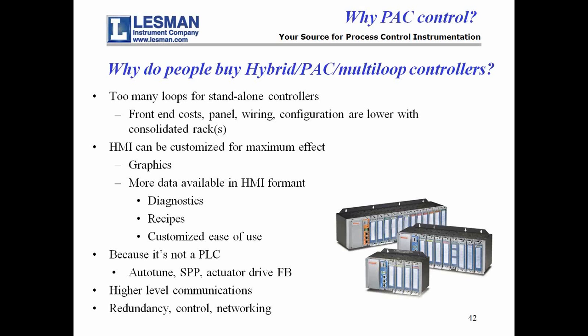And SCADA is really a word that has a lot of different meanings out there. I've heard it used, I just collect lots of remote points from remote RTUs. An RTU is a remote terminal unit. It's a box that has some I/O in it and then communications out.